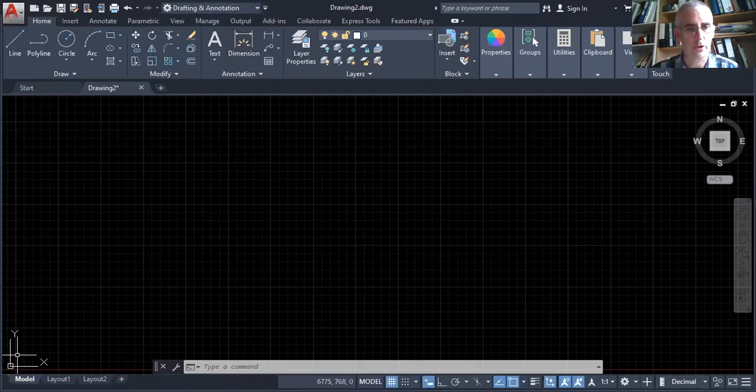Down here, we've got our UCS. Now you can move the UCS with various commands. We're going to leave it here at the origin. So if you can imagine this here being a set of coordinates, and you've got 0, comma 0. So you're along your x-axis, 0 would be here, and your y-axis 0 would also be there. So if we were to go to, say, 50, comma 50, it might be there. 100, comma 100 might be there. If we were to go, say, 500, comma 500, that coordinate might be somewhere here. Okay, and we'll be showing you how that works in a little while.